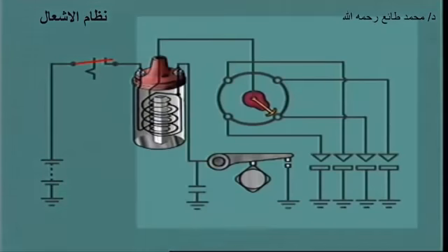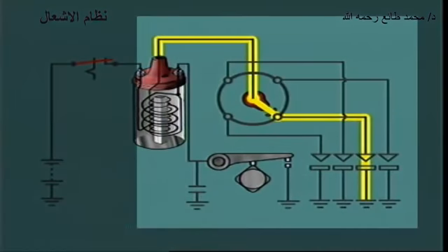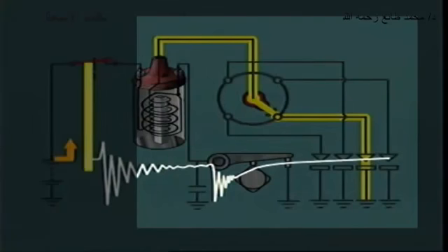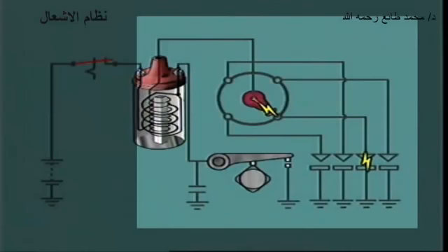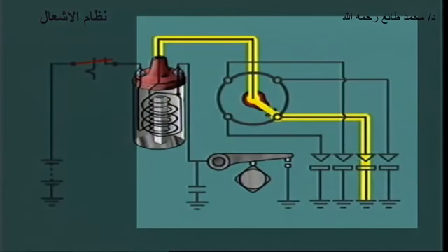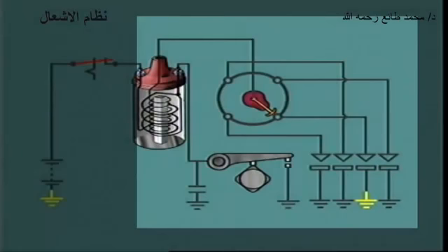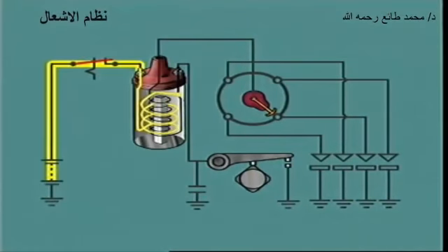As the high tension voltage builds up across the ends of the secondary winding, a voltage level is reached where the spark plug gap suddenly becomes conductive. A spark then bridges the gap between the rotor and the distributor cap segment, and also the gap between the spark plug electrodes. The secondary circuit is from its connecting point at the primary winding to the spark plug and across its electrodes to ground. From there, it is completed through the battery and primary circuit back to its connecting point.